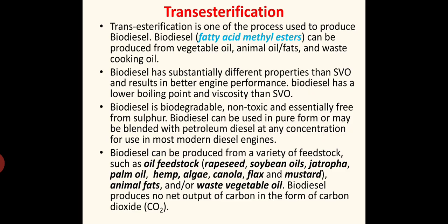From all these things we are producing biodiesel, but the conversion process will differ for the different oils used. If you are producing biodiesel from animal fats, then the temperature provided will be different and the cooling time required will be different. Everything will be different compared to biodiesel prepared from jatropha. Identifying the optimum temperature and cooling time is very difficult. We have to do a lot of experiments to find these values. Once they are identified, it is easy to produce biodiesel from all these oils.